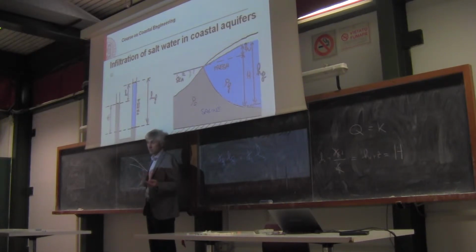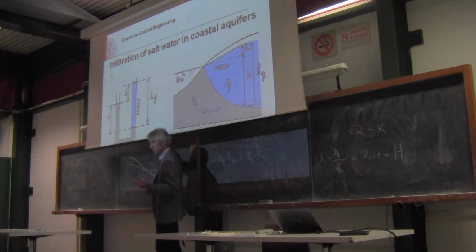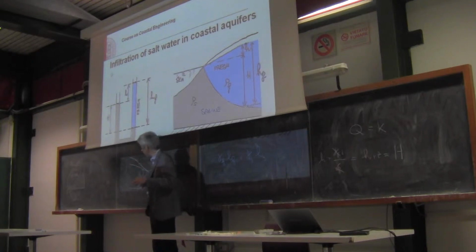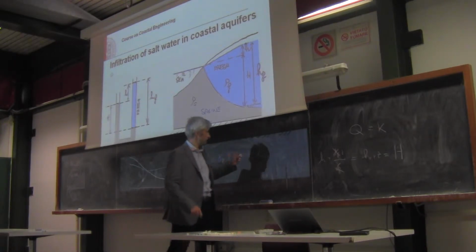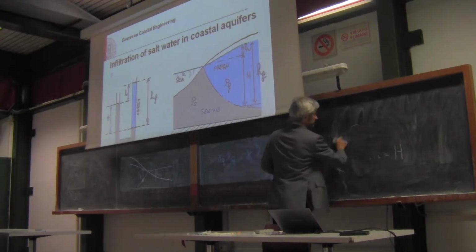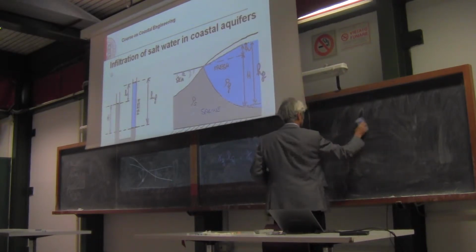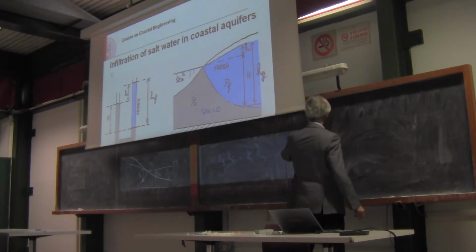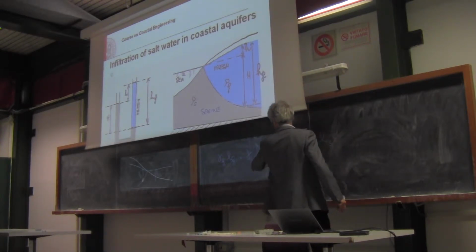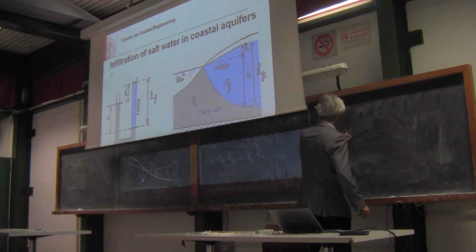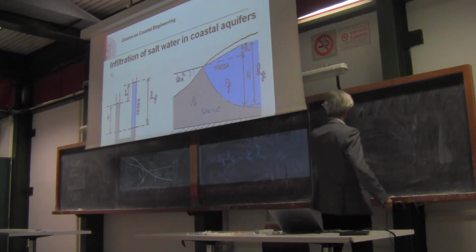And in order to locate where is equilibrium, let me compute in an explicit way HS, because the seawater level is fixed, on average is fixed, and therefore if I compute HS, I uniquely locate the position of this particle, and therefore I can write that HS is equal to gamma F divided by gamma S times HF.